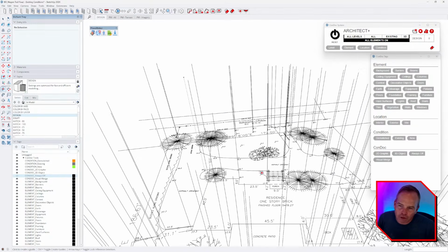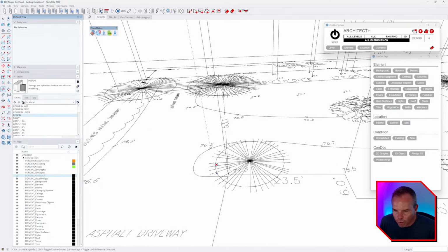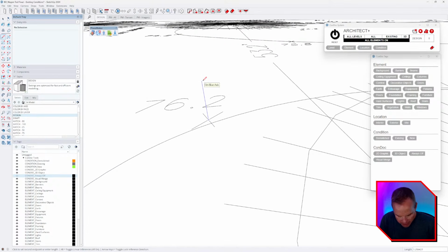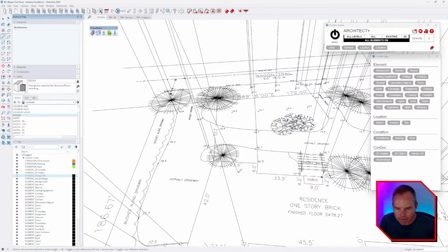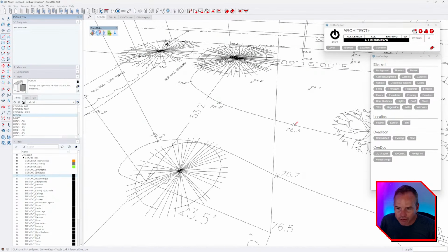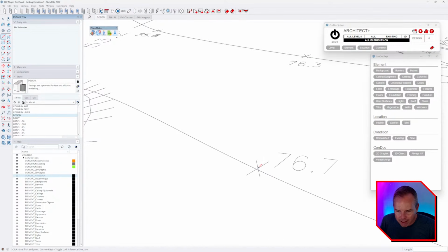But I was going through and I was going to show the mistake that I made. So yeah, that's a good point. The ideal way to do this is to draw with the tape measure tool, tap Control, Option on the Mac to add those guide points. But I was going to show you the mistake I made and how I fixed it.